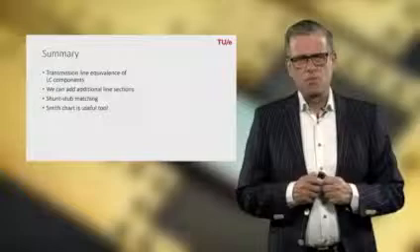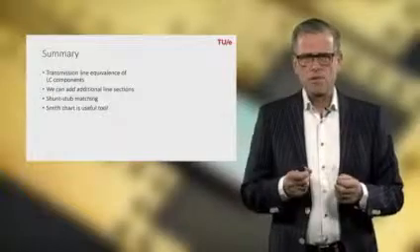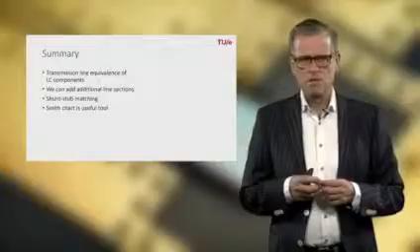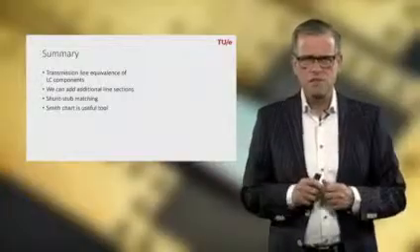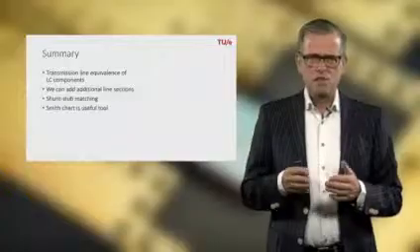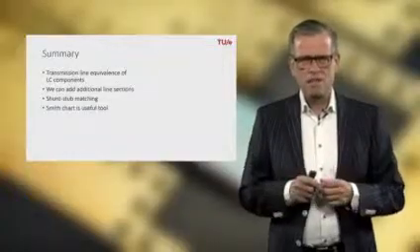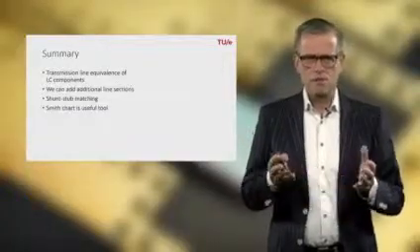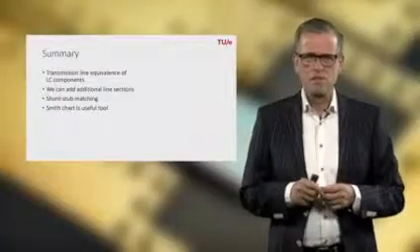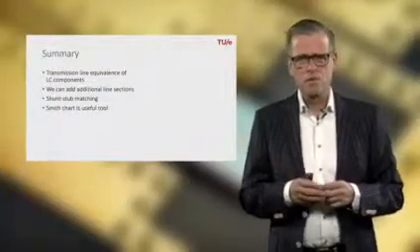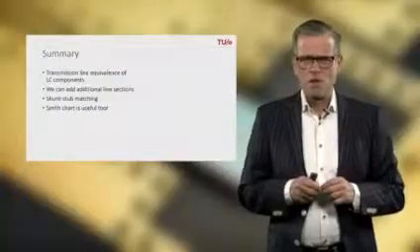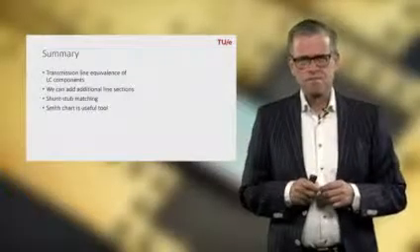So to summarize this web lecture, we have first introduced the transmission line equivalence of LC components with Richards transformation. On top of that, we can also add additional line sections, and we have applied that to the case of shunt stub matching. And we have seen in the example that the Smith chart is again here a very useful tool to visualize the concept of matching.